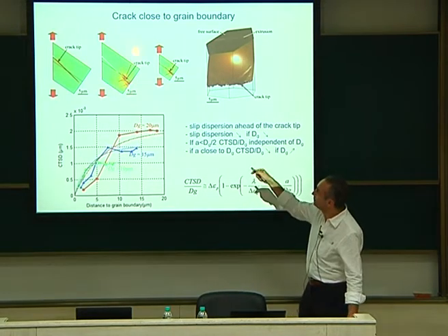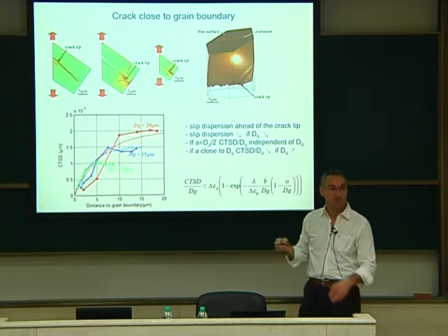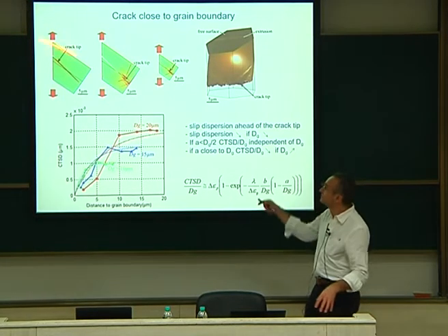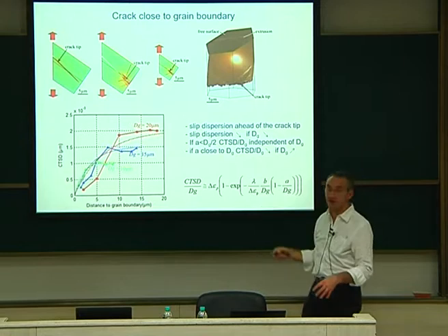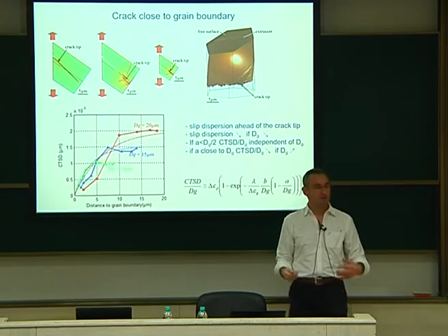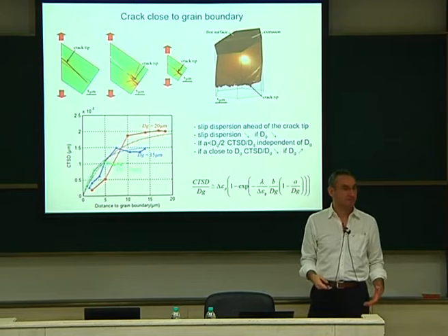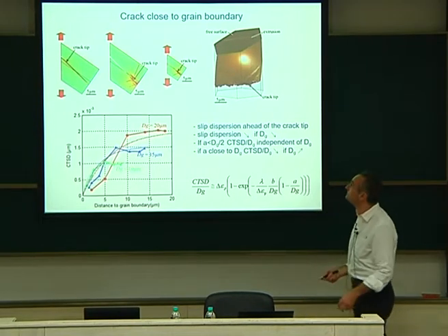So because of that, you have a lot of slip dispersion. Dislocations cross-slip and go everywhere. All the slip systems are now activated, you see. So you have some large dispersion like that that will slow down your crack. The crack will be slow, actually it will blunt the tip and slow down the crack advance. Okay, this is the process. This is the main idea.